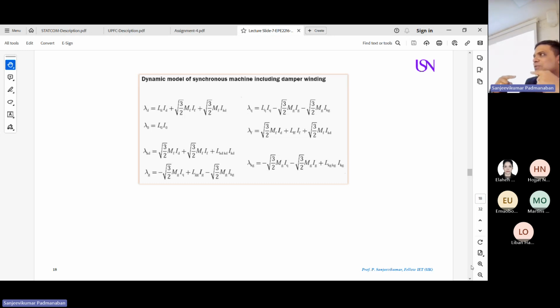They are opposite. So this resultant will make the brushes in your armature shift from the neutral axis. At the neutral axis, you have zero flux, zero current flow. That is the principle of the electric DC machine. So this neutral axis will be shifted a little.